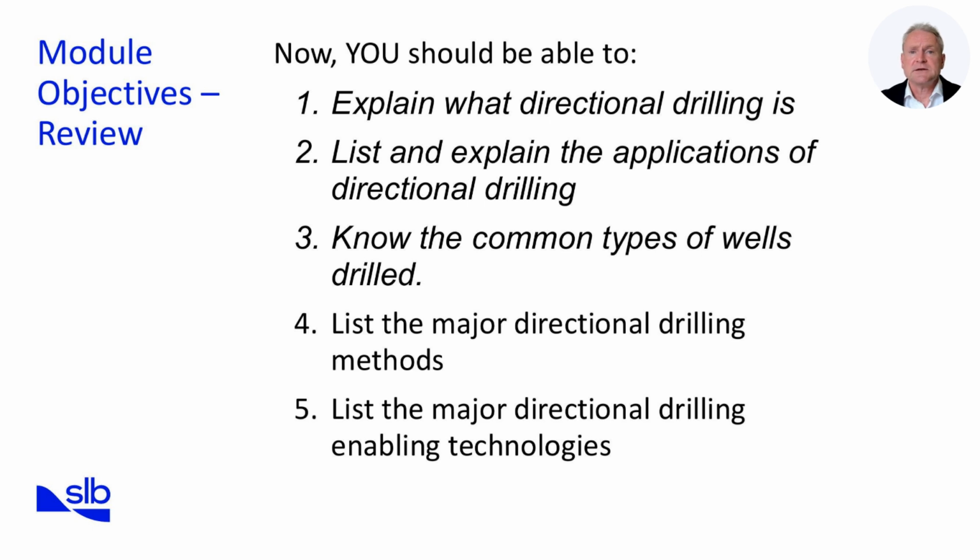Alright, as we reach the end of this module, let's take a moment to review what we've covered and reflect on the key learning objectives. In this submodule, which is 2 of 3, we covered some of the calculations used in drilling for surveying, including how to determine the radius of curvature and build-up rate. We established the rate of build-up into short, medium and long radius wells. We looked at the 3 different ways a deflection could be achieved in the past through the use of whipstocks, straight motors and bent sub and jetting.